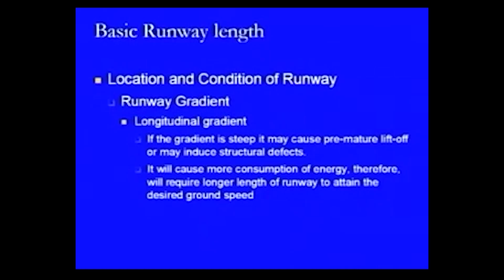Then it will also cause more consumption of energy and it will therefore require a longer length of runway to attain the desired ground speed. So, that is the effect of a greater longitudinal gradient being provided along the runway length.